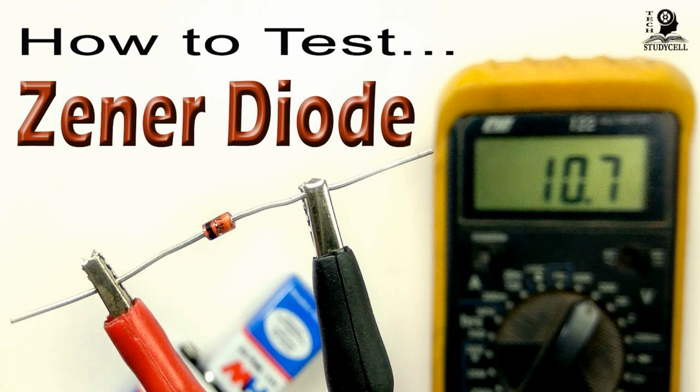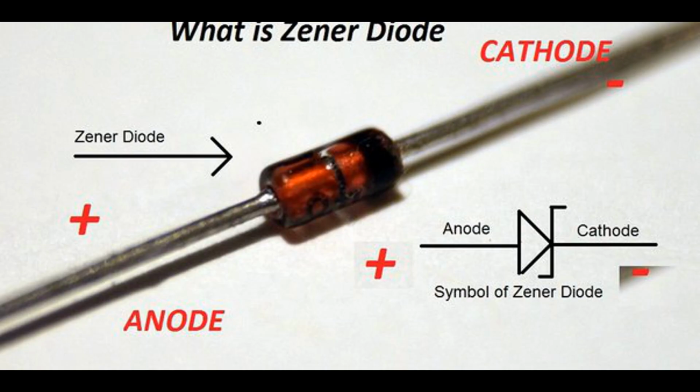Switching voltage regulators. Switching regulators work by switching the input voltage on and off at high frequencies, and then filtering and regulating the output voltage. They are more efficient than linear regulators but are more complex. IC voltage regulators. Integrated circuit IC voltage regulators are specialized chips that incorporate all the necessary components for voltage regulation. They are available in fixed or adjustable output voltage configurations.